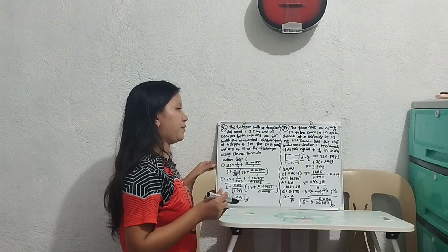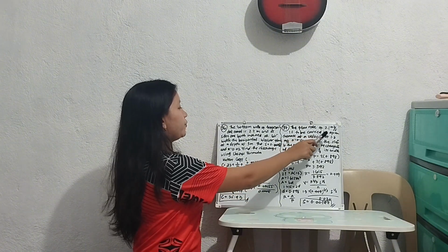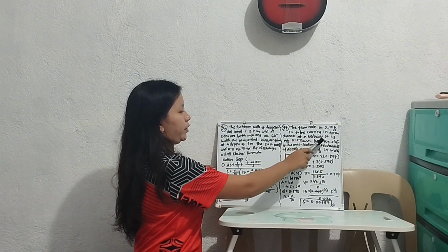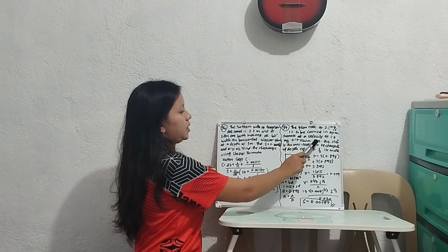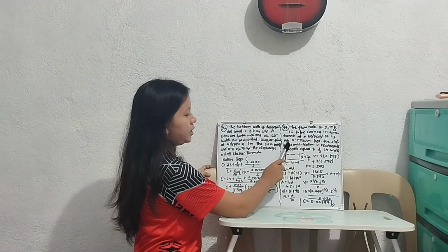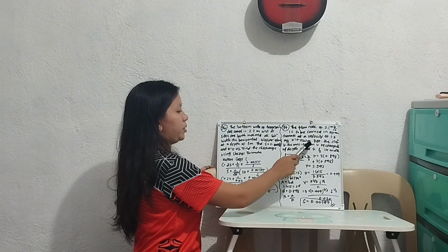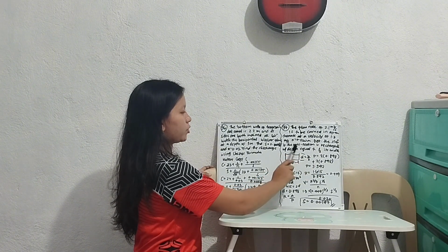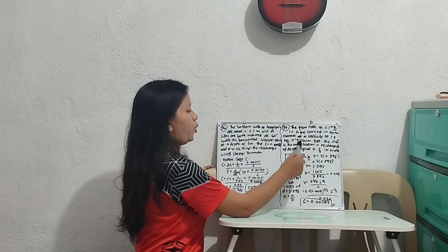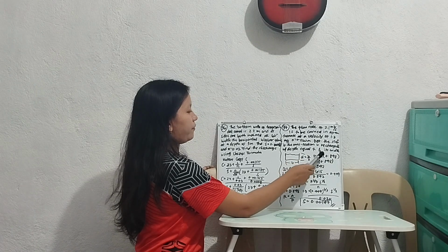For number 37, the flow rate of 2.1 cubic meters per second is to be carried in an open channel at a velocity of 1.3 meters per second and at a roughness coefficient of 0.020. Determine the slope. The cross-section is rectangular with depth equal to 1/2 its width.